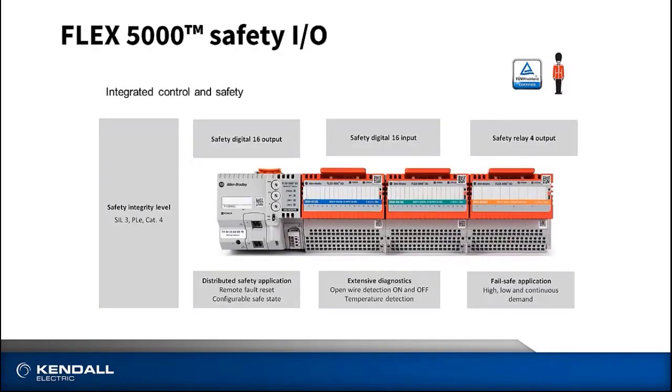Taking another look at the modules here, starting from the left, the adapter in this case is a dual channel wired Ethernet adapter. This is the adapter that puts the modules out on the Ethernet IP network. There is an option if your architecture demands using fiber optics. You can also choose a fiber optic adapter for this I/O structure.